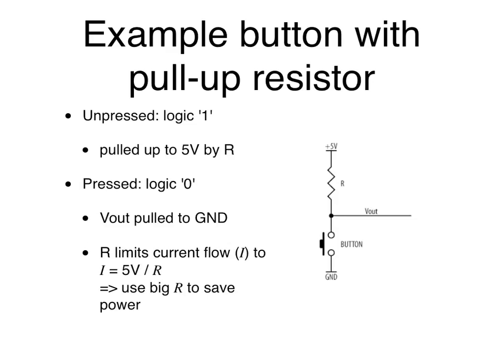And that's a resistor there, really for the purpose of limiting the current. Okay. So, for example, if you have a push button, that's usually the way it's connected. That is, the button is usually disconnected, right? And when you press it, it connects the two poles or two terminals together. It could be just a single pole. It doesn't have to be contact like that, right? But you get the idea.